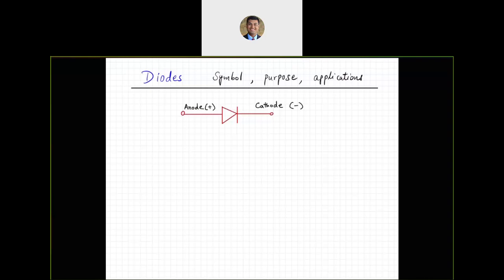And this guy is the positive terminal. And I can denote the current that flows through the diode as ID, and I can also talk about the voltage that is across the diode. I can say maybe VD. So I've got VD to denote voltage across the diode. If I take two voltage probes, one of them on this end and the negative side of my probe on this end, then I'm going to be measuring VD, voltage across the diode.